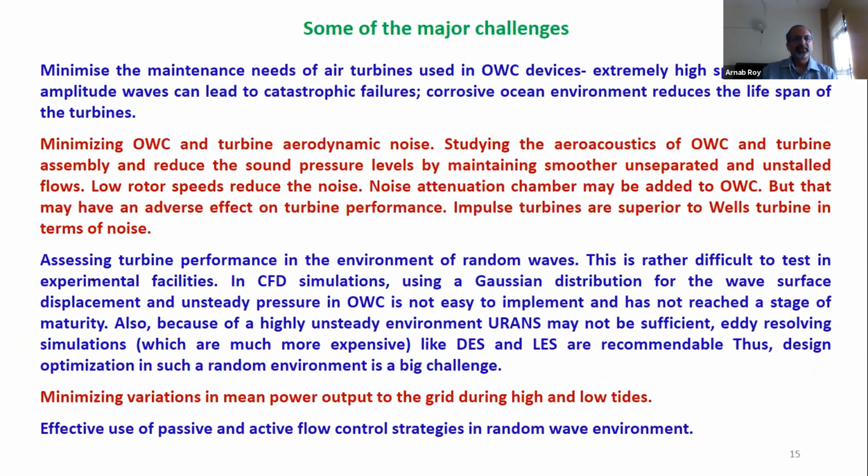So let's look at a few challenges. When we are talking about actual operations of these air turbines in OWC devices at site, they are basically functioning under adverse conditions. There could be extremely high speed waves, high amplitude waves, which could lead to catastrophic failure, typically mechanical failures. And then there is the corrosive nature of the ocean environment, which could be very detrimental for the turbines. So improved materials could be one direction in which the